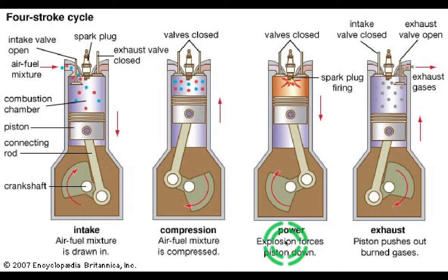So we see here they are calling it explosion, but explosion is not the correct word, although you can say it that way. This is slightly less than an explosion, because it burns in a manner which is suitable. Let's not get into that, we will deal with it later when we study knock detection and control. So when the piston is up, it has compressed everything.